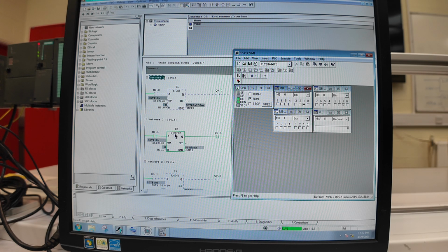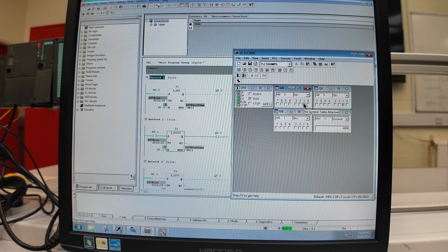this is an off-delay timer, so as soon as we set the memory bit, our output is set as well. As soon as we set our memory bit at 0, the time is running, and 10 seconds later, the output gets the value 0 as well. That's the same as with the other timer, which means we can restart it. This timer is just reacting on the negative edge of our input signal, and as soon as we put in a positive edge it stops, and as soon as we set our memory bit to 0 again, we have the 10 seconds count on again.